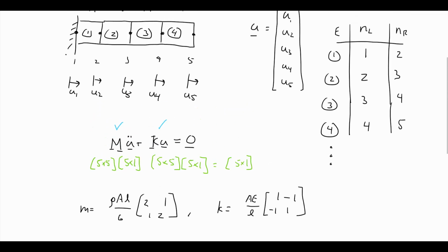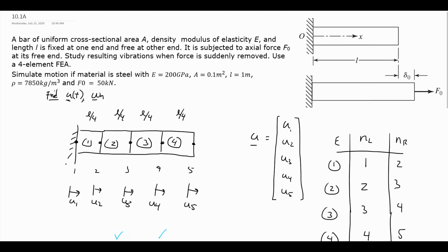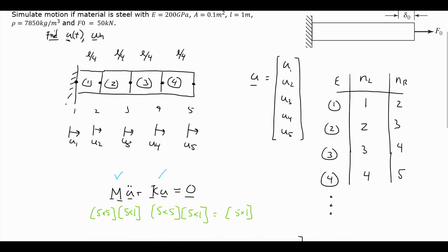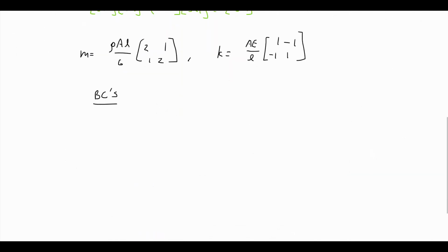So going back up here, if we remember from the analytic problem, we had 2 boundary conditions. We had the displacement at the wall was 0, and the axial strain at L was 0 as well. So I'll write those down. So u of 0 should be 0, and u prime of L is also 0.